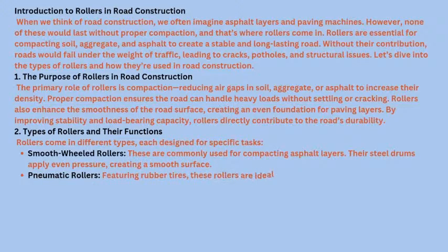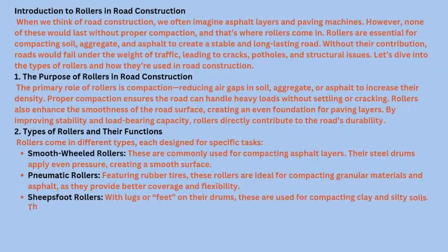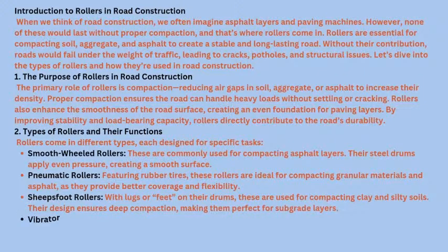Pneumatic rollers. Featuring rubber tires, these rollers are ideal for compacting granular materials and asphalt, as they provide better coverage and flexibility. Sheep's foot rollers. With lugs or feet on their drums, these are used for compacting clay and silty soils. Their design ensures deep compaction, making them perfect for subgrade layers.